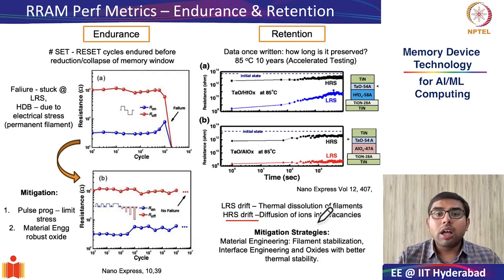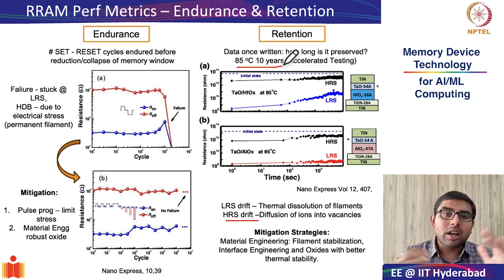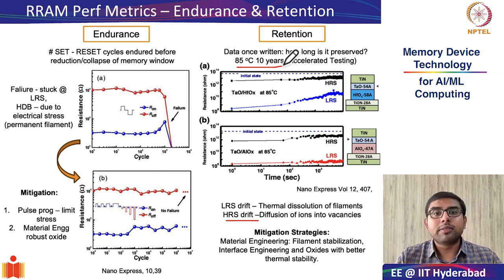So as we have seen, thermal energy is a main factor which can degrade the retention of RRAM devices, and therefore it is absolutely essential, to claim that you have a viable RRAM technology, that you perform accelerated testing, which we have looked at in detail for other non-volatile memories, showing at least 10 years of memory at 85 degrees Celsius.